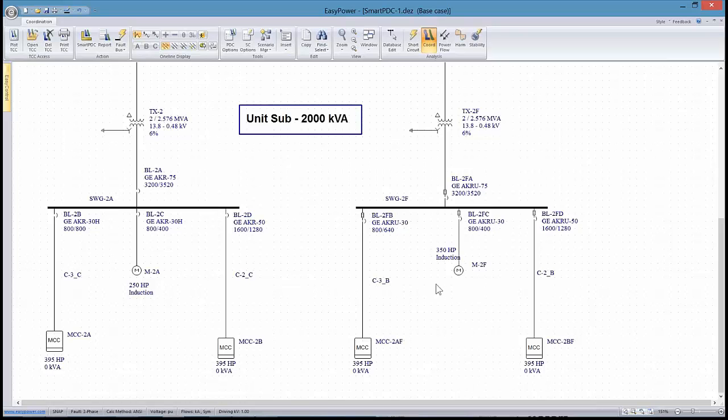Whereas if we have a very large motor that has a lot of inertia in it, it could actually be considerably damaging or susceptible to a very long fault, in which case your protection scheme would change.